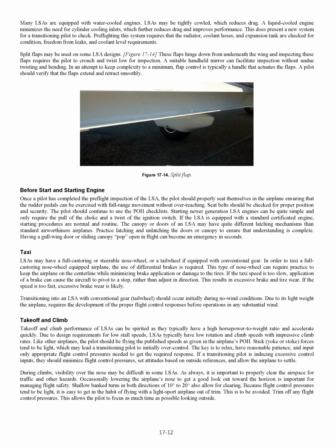During climbs, visibility over the nose may be difficult in some LSAs. As always, it is important to properly clear the airspace for traffic and other hazards. Occasionally lowering the airplane's nose to get a good look out toward the horizon is important for managing flight safety. Shallow bank turns in both directions of 10 degrees to 20 degrees also allow for clearing.